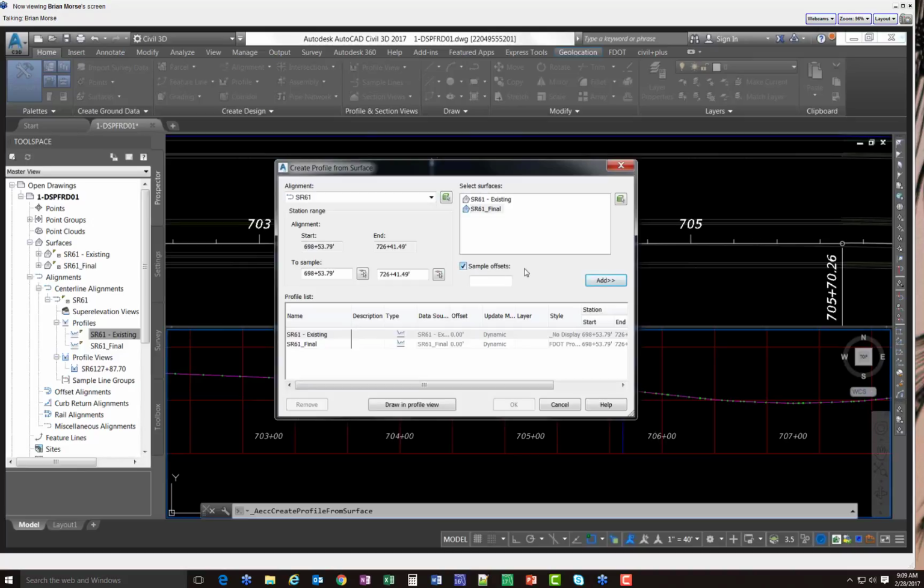And you've probably discovered it in like 5 days, and it took me 10 years. So here's how it works. I went to the help file and I said, hey, this says offsets with the letter S on there. So do you think I can put in more than one offset here? And the answer is yes. So this is the syntax of it: left is going to be a minus, right is going to be a positive, and if we wanted to find the outer offsets, then you just keep separating that with commas, and there you go.